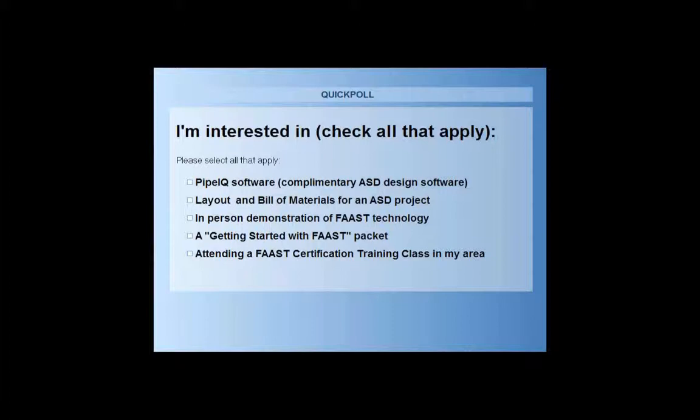If smoke detection is required, or you'd like to provide that, because obviously smoke detection is an advanced detection over heat detection. Yes, an elevator shaft is an ideal application for it, considering the harsh environment that is present with an elevator shaft. Air sampling would be ideal for that application if you wanted to provide smoke detection. But traditionally, it's a heat detector or a heat device that would be used for an elevator shunt trip.